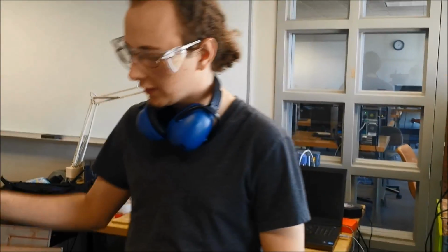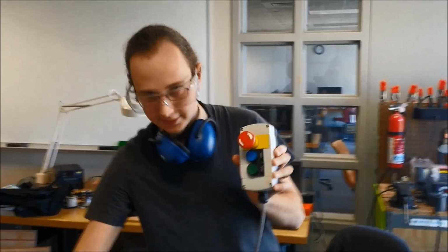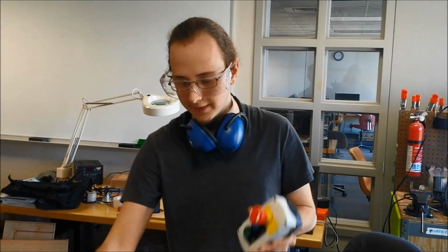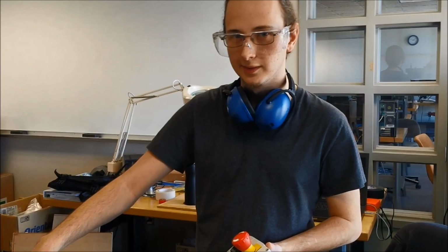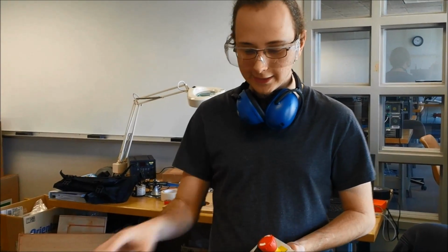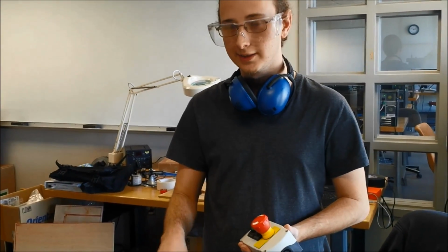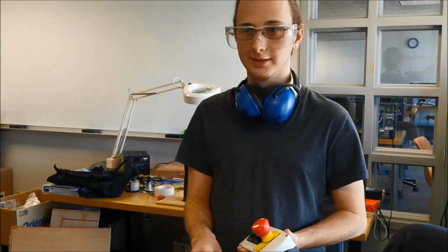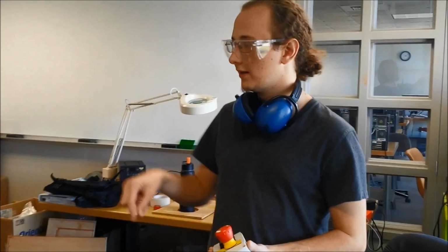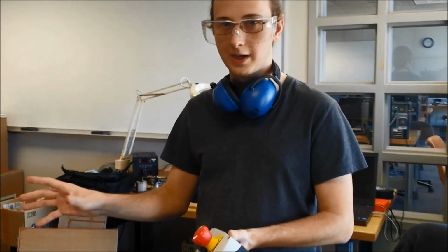The spindle automatically turns off. We turn off our dust collection and we can go look at our part. Now, should something go wrong, this or this button will stop the machine. It will turn the spindle off and all the motors will turn off. It will not move, so it's going to stay in your material. So what you need to do at that point is use the software to manually jog using the up, page down buttons, and lift the Z-axis first, then move it out of the way. And then you can fix whatever problem you have.